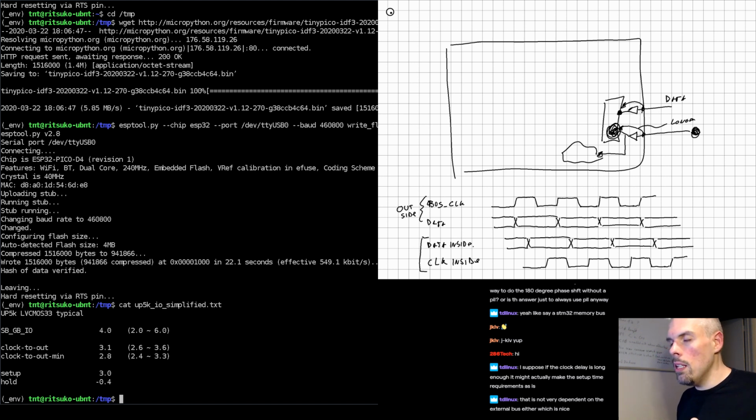But alternatively, if it turns out that it doesn't because of these reasons, again, you can play with input and output delays. Like the iCE40 doesn't have any of this, right? But in the ECP5, again, at this point here, I mean here and here, you can have programmable delays that you can use to adjust your margins if you find they're not good enough.